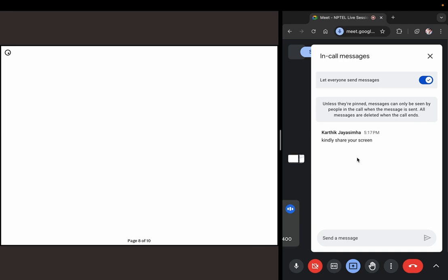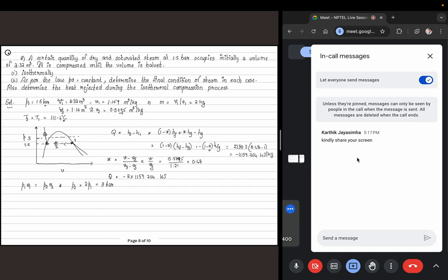So again, we follow the same process as we have done before. You know P2, and your V2 is already known to be 0.5795. So your vapor fraction is approximately 0.5795 divided by the specific volume in the vapor phase at 3 bar pressure, which is 0.6058.